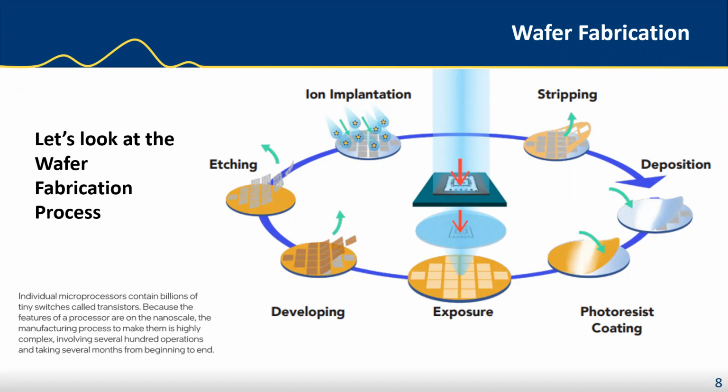You see, particle monitoring is really important. Here we see the life cycle of a wafer. As we just covered how wafers are made prior to the fabrication process, we see here that the process starts with the photolithography stage, where the tiny circuits are masked onto the wafer and developed and then etched, and implantation takes place, followed by stripping and deposition. This process is repeated as the many IC layers are built up onto the wafer.